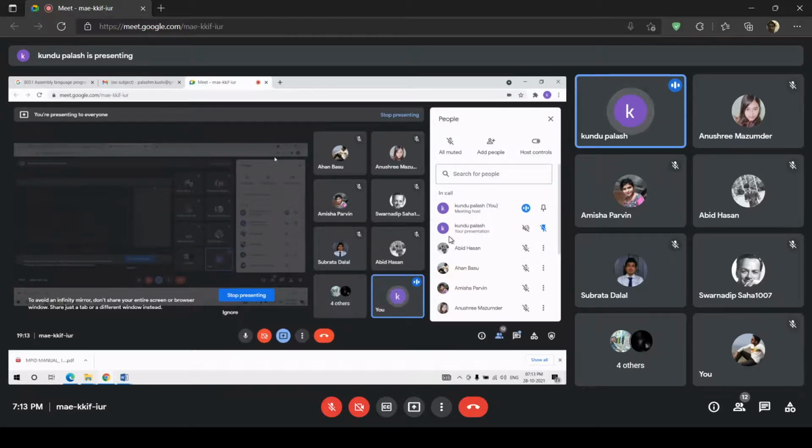If the number of data bytes is n, the extra bits required are at most 3 times n. So the total number of bits for asynchronous communication will be 8n plus 3n, which makes 11n.